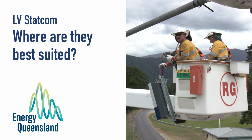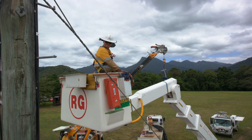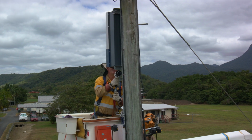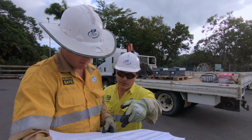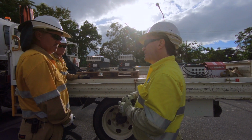Where on our network are Statcoms best suited? Statcoms are designed to be installed on semi-rural and urban overhead low voltage networks that are experiencing issues with sustained and short voltage fluctuations. Each site is assessed on a case-by-case basis, so if there's an area where you think a Statcom may be able to resolve an issue, talk to your region's asset management team.